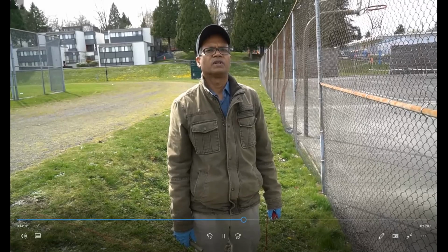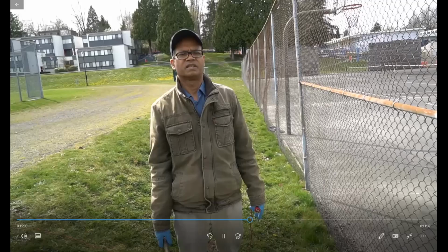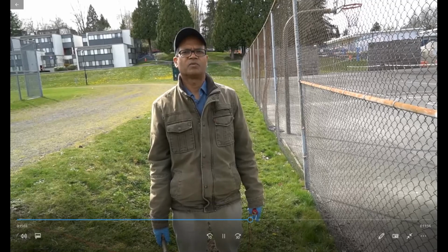So now we will assume that a short circuit happens somewhere close by, and there we'll put this probe, and we'll use our meter, and we'll discuss how we have to measure the touch potential. We'll measure the touch potential from the grounding grid or whatever is connected to the ground grid 1 meter away from there. So 1 meter represents one step. It is definitely a little bit higher than one step, but that's the standard we use.